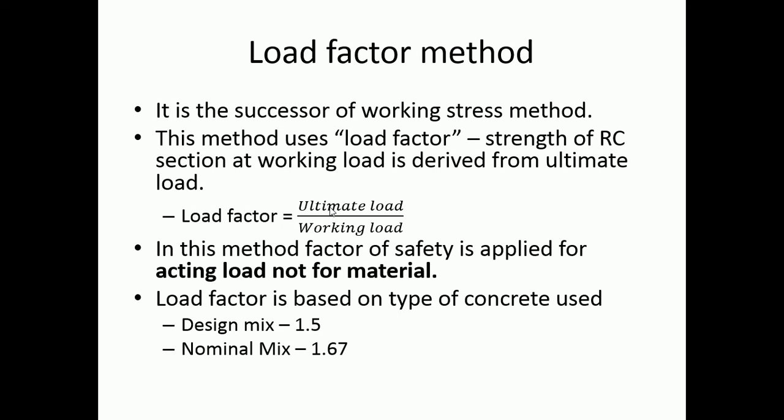So for that ultimate load we'll be doing the designs. So that is the main concept behind the load factor method. In that method, the load factor is actually applied for the load and not for the material. And the load factor is based on the type of concrete used. If you are going with the design mix, then you can have a load factor of 1.5, or if you are going with some nominal mix, then you can have the factor as 1.65.